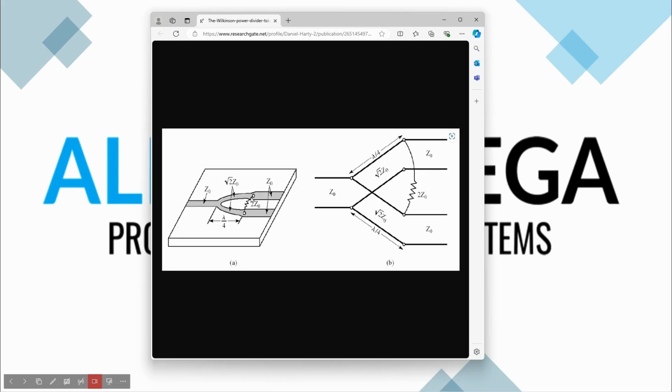It has this resistor between the two output ports, this being the input. This resistor allows complete isolation between the two outputs, which is really useful in RF communication systems to be able to prevent crosstalk between channels. So it's a very common power divider to use. Also, reciprocally, it can be used as a power combiner if you input your signal in the outputs. Make your outputs your inputs, and then that way it's a combiner.